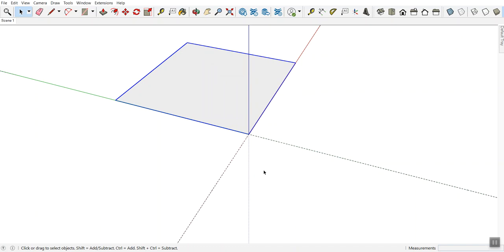Everything looks and feels the same, except that those dotted lines we had in the middle are all gone. I still have a 2D object, and I still have it selected. You can tell that by the blue, blue, blue, and blue. Now if I hit O for orbit, or again, the speed keys that I use all the time are O for orbit, Z for zoom, T for tape. Those are just some of the absolute basics. I don't even think about it anymore, but you can go up here to orbit.